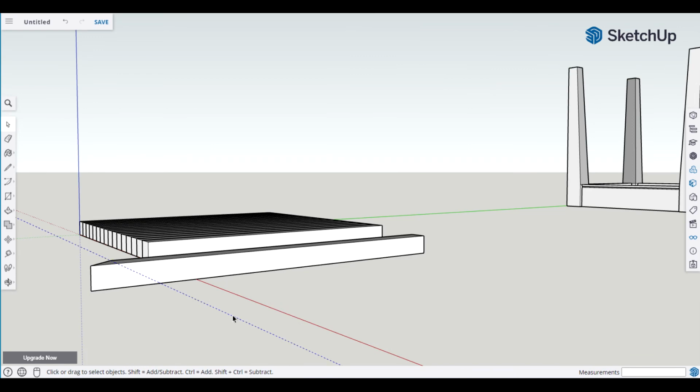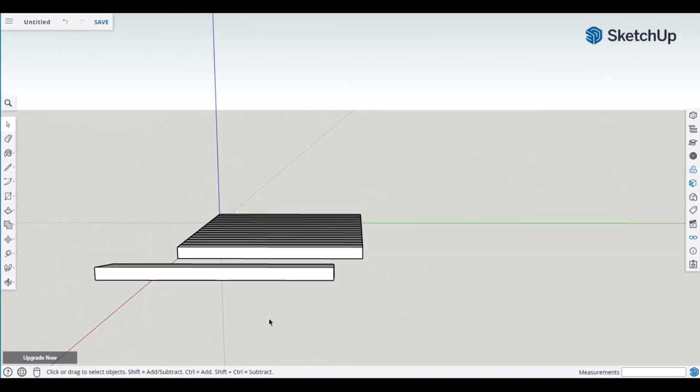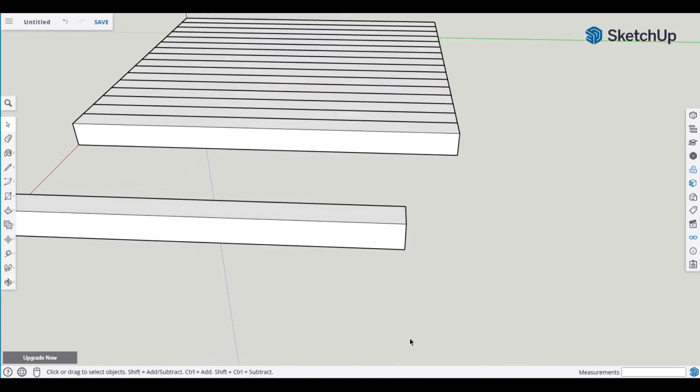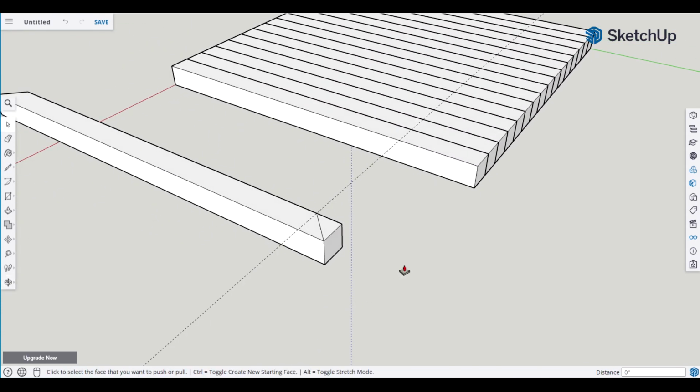Let's take this highlight, delete it, go to this side here, bring it down. Let's do the same thing. Anywhere along here, bring it 1, enter, space. Again, our miter is going to be this way. Select L for the line tool. Snap it to the intersection. Snap it to the endpoint. Space bar. Rotate. P. Click. Bring down. Click. Space bar. Highlight. Delete.